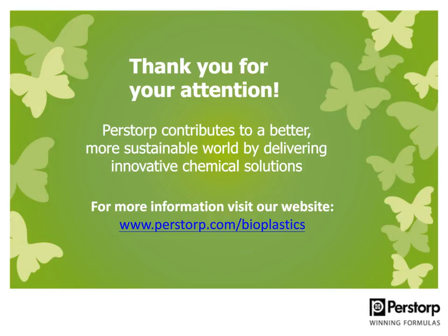Thank you. Next one is, which additive levels do you suggest to modify PLA grades and improve the mechanical properties for injection molded articles? It depends on how much you would like to modify the properties, but I suggest that in injection molding grades you can add between 10 to 30% of the PCL to see if you reach the mechanical properties that you would like to improve.